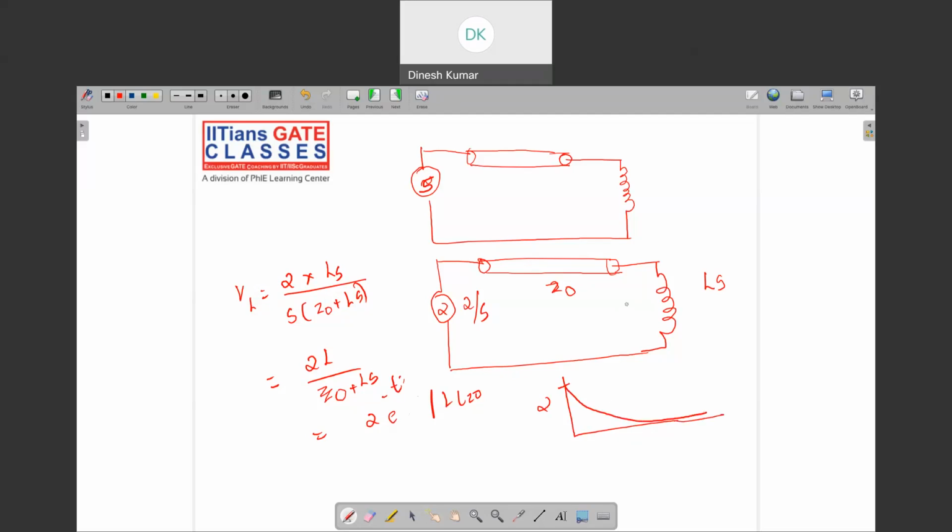Because when we open circuit this, this will see 2 volts. So we have to terminate this with some impedance of Z0. Then it will come down to 1. Now the time constant will depend upon these two things. Like this we can derive for different kinds of loads.